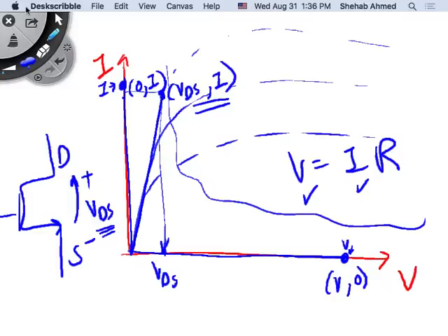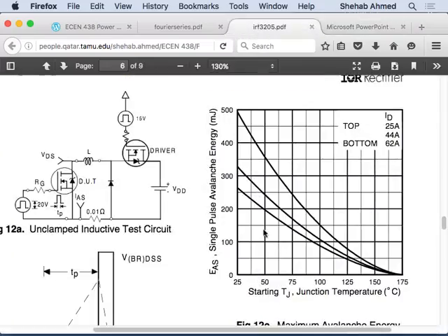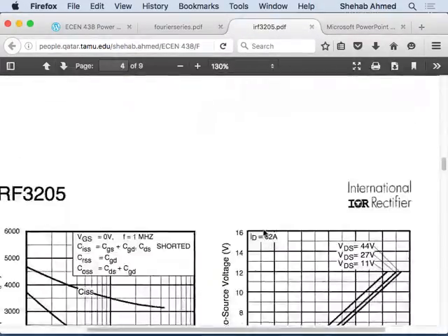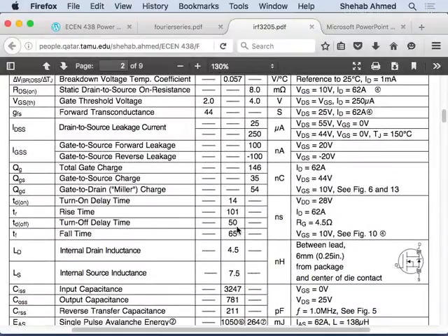Okay? So ideally, I would like to increase switching frequency. I cannot because of switching losses. That's one thing. And I cannot because of the limitation on rise times and fall times that we have in the switches. We saw those in the datasheet. There were rise times and fall times in the datasheet. They limit your ability to actually produce a proper turn-on time.